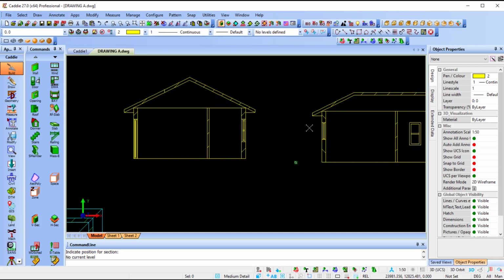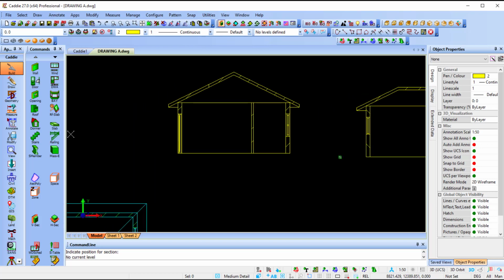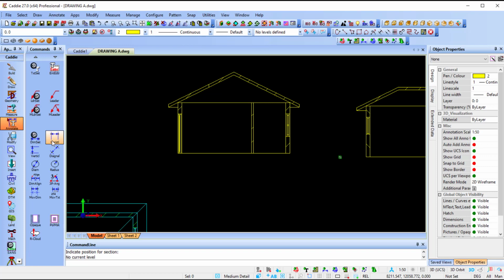So when it comes to the dimensioning, what I'm going to do now is I can only apply to this one window and it will be applicable to all 4 of the other windows. So first of all, let's go to the dimensioning so that I can explain to you the difference, because when it comes to the SANS calculations, you will see that it's going to ask you for a P value and an H value.